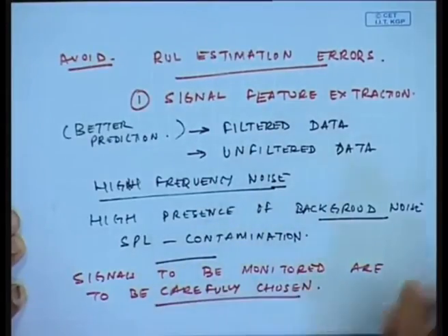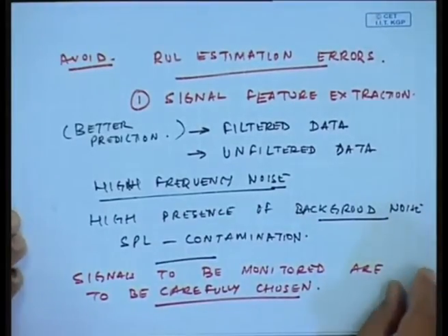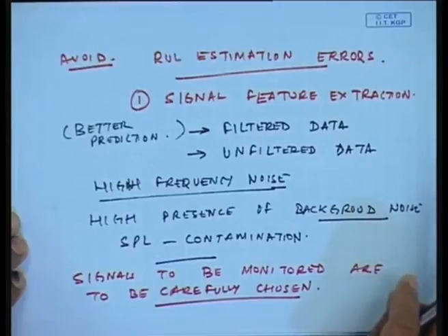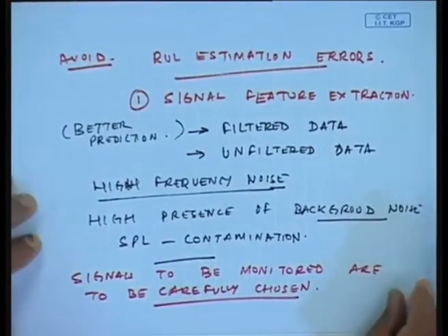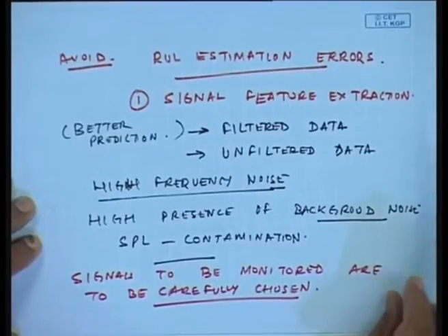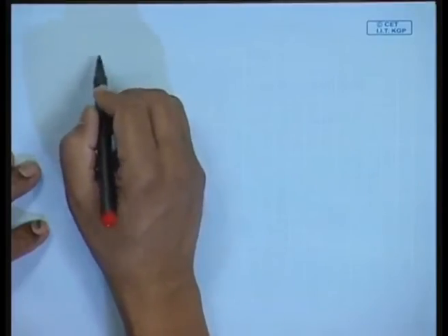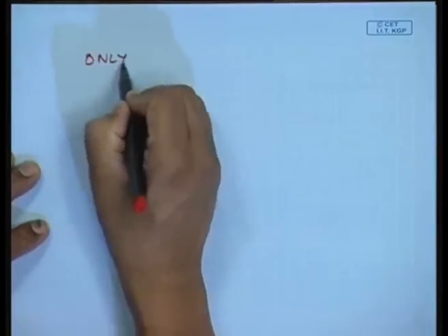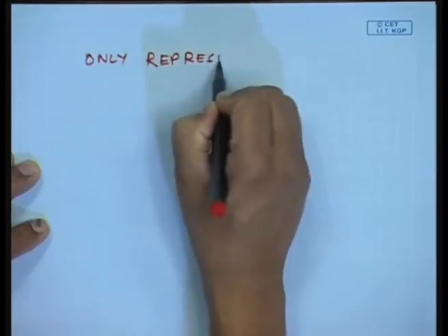That is very important. In this experiment of ours, though we measured acoustic emission and overall sound, in the later stages we did not use them for the estimation of the artificial neural network because of the fact that they were contaminated, and then we are not giving in signals which are only representative of the machine or the process.